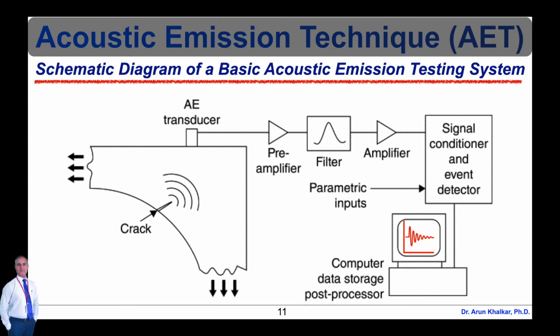Next, the signal is relayed to a bandpass filter for elimination of low frequencies common to background noise and high frequencies. After completion of this process, the signal travels to the acoustic system mainframe and eventually to a computer or similar device for analysis and storage. Depending on noise conditions, further filtering or amplification at the mainframe may still be necessary.